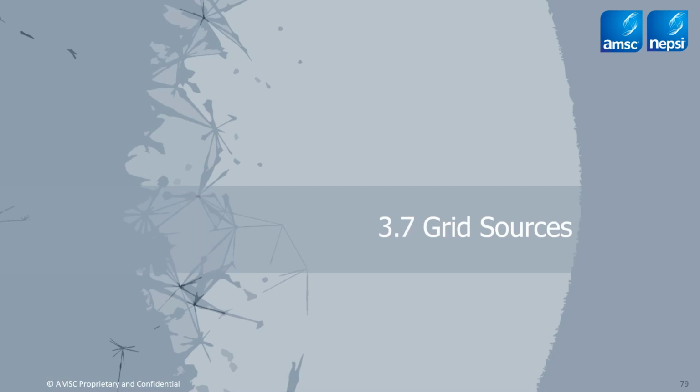And that's important to know, because a lot of times we're thrown curves or results out of a harmonic study, and it's got these peaks and these valleys and all these results showing up, and you're like, wow, there's a lot of stuff moving around. True, but at the ground floor, this is how you model it. I can attest to that because I've modeled harmonic systems. I've written network analysis routines, and when you're simulating harmonic corrections, this is exactly how you do it. It's just that Y bus can get big, okay? I mean, it can get large.